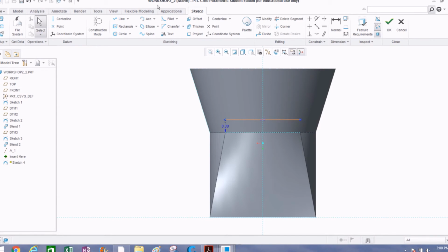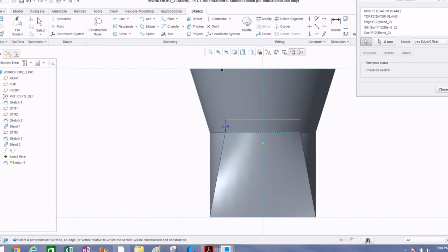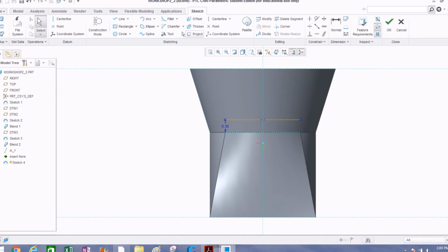Now we're going to go ahead and, no, actually, we're going to need this top surface as well, so we'll reference that too. We'll reference that top surface and get everything we need up front here. Click line, come off to the sketch, see we're grabbing the point, click and drag up to the side. You can see now we can move it along this line. It's going to grab the line on top. We want it to be parallel, because that's kind of what our drawing looks like there. Obviously you'd specify it if you need it that way, but we're going to do it this way. We want parallel. Click once, and now we're going to continue sketching off to the side.